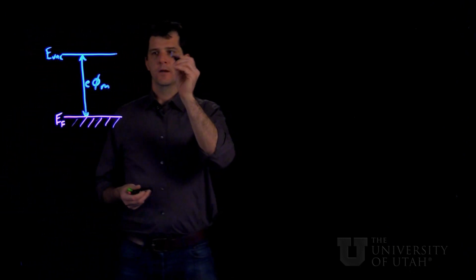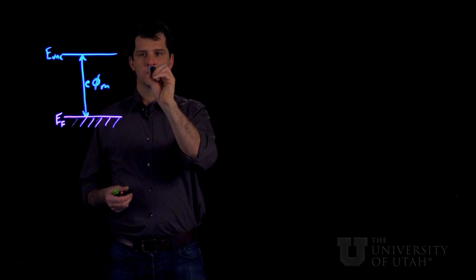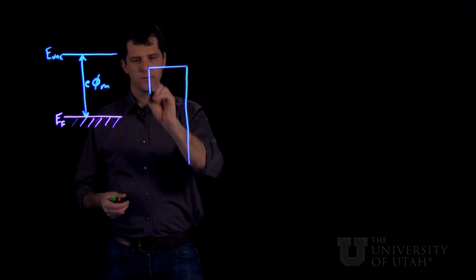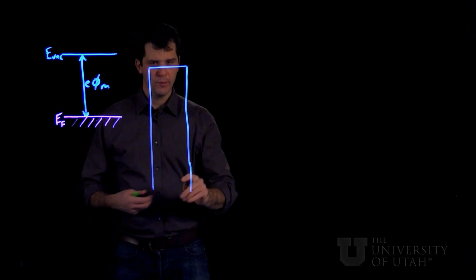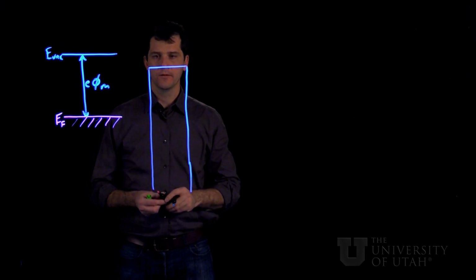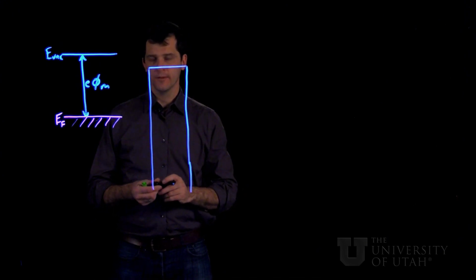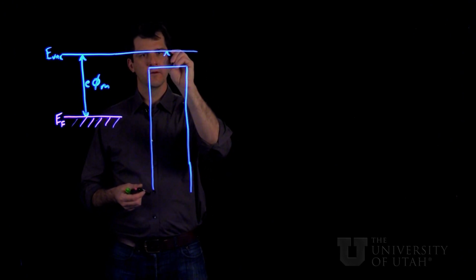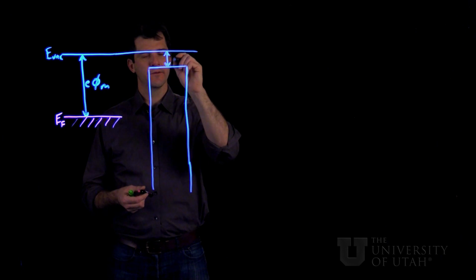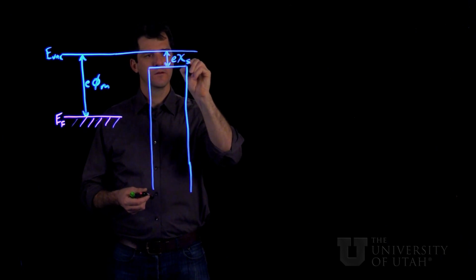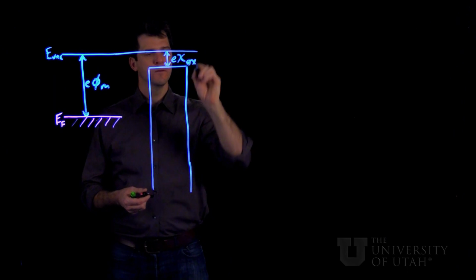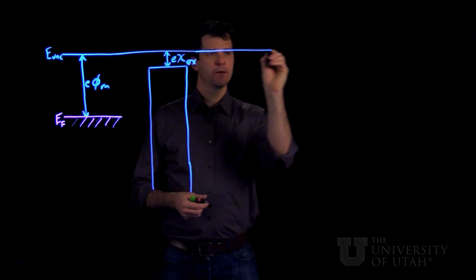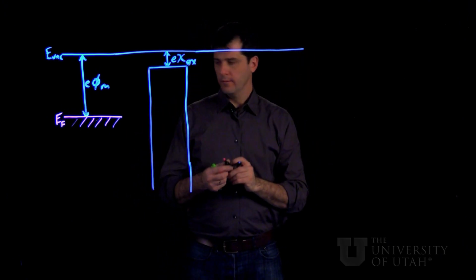Okay. The oxide, in the absence of any built-in voltage, looks something like this. You have a band gap of something between 8 and 12 electron volts, and then it has a very small, usually assumed to be very small, oxide electron affinity.